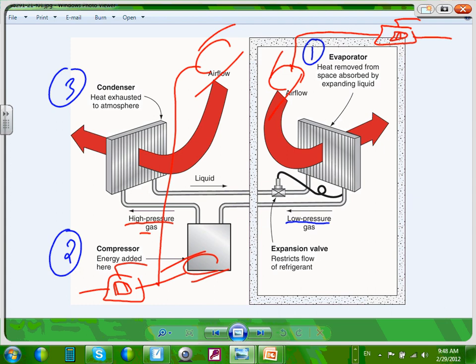So if you go next to the air conditioning unit, guys, and you look at the evaporator, the condenser, the fan moving the air, you're going to see that it's very hot right at the top of the air conditioning. Very hot air coming out of it. So all the heat that comes out of this room, we put high pressure, we pressure it to make the system work better. We send it through these coils, and then we blow a big blower right through it. So it takes the heat out of that high pressure coil and throws it into Mother Nature, outdoors.